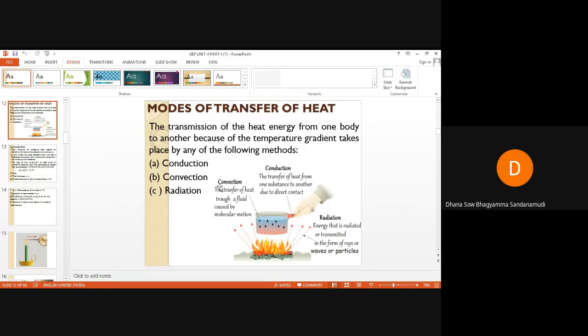In this mode of heat transfer, the heat transfers from one part to another part of a substance or a fluid due to the actual motion of the molecules. The rate of heat transfer depends upon the difference in the fluid density at different temperatures. So the fluid density will be varying as the temperature varies.